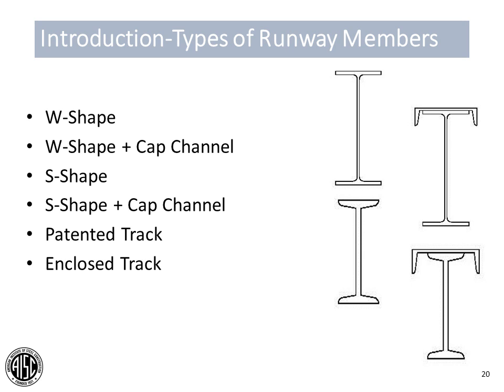If you have a longer span member or a highly loaded member, you may want to utilize a cap channel on top of a wide flange. This typically will not be used to resist lateral forces of these underhung crane systems, but rather will be used to brace the compression flange and increase the lateral torsional buckling stability of your runway system.